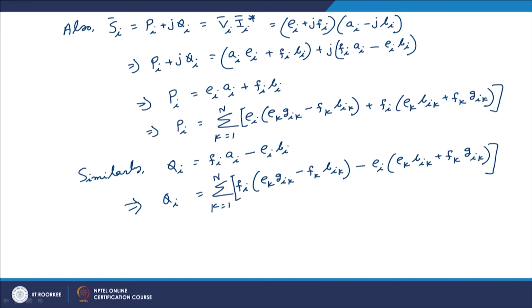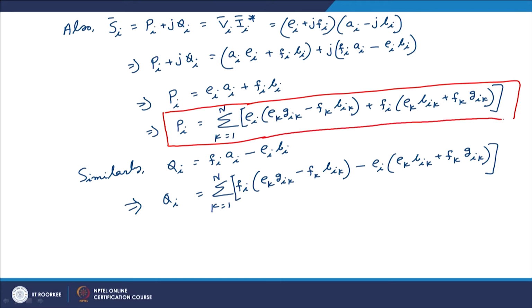Therefore, these are the two expressions of injected real power at bus i and injected reactive power at bus i in rectangular coordinate.